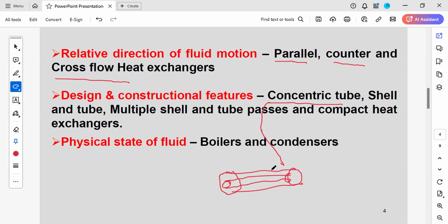So that kind of heat exchanger is called this. Here hot fluid will be flowing in, THI, and here hot fluid will be coming out. Surrounding it will be the cold fluid in the annulus portion, TCI, and here TC naught. So this will be the concentric tube exchanger. This is a concentric tube heat exchanger or tube and tube heat exchanger.